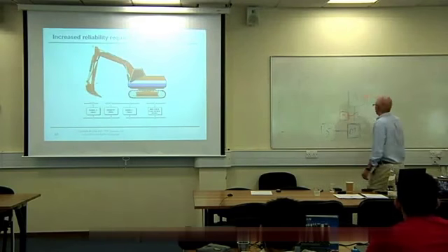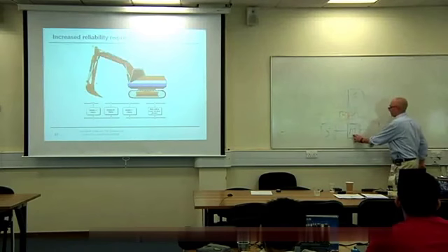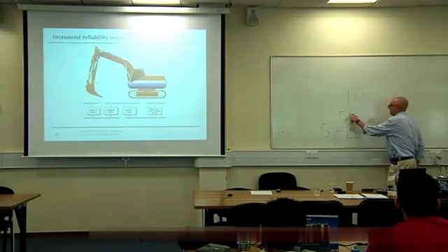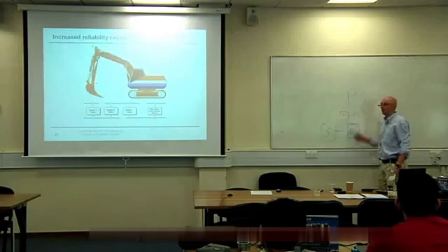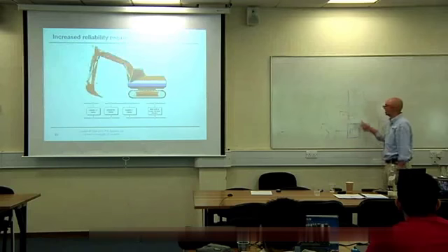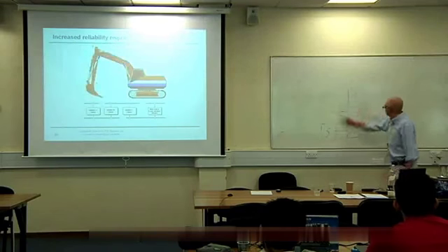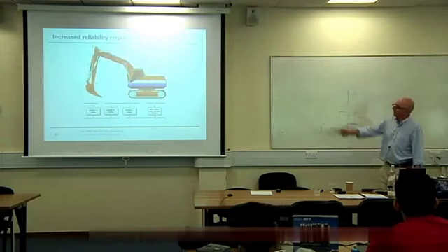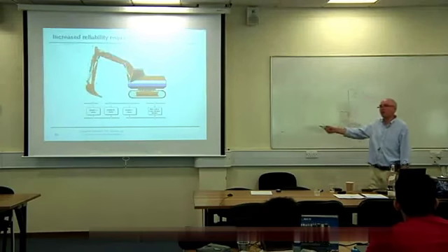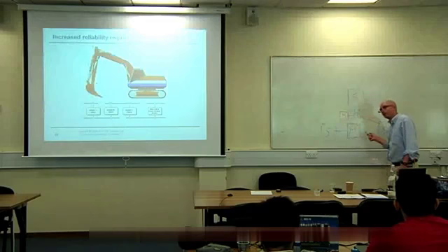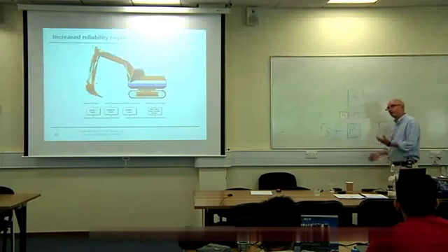And we can make that work. We can have this one generate messages, and these slaves echo those messages, so this master can work out whether everything else is connected to the bus, and this one can step in if particular problems occur. Challenge with this, that's got cheap wiring. This wiring gets more complicated and more expensive. It's all swings and roundabouts.